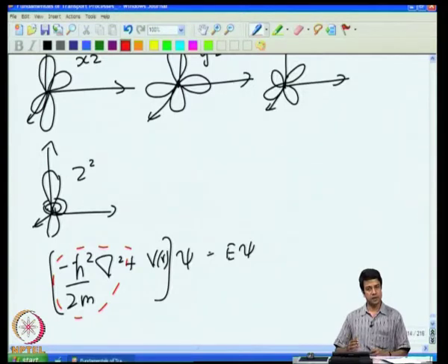For the unsteady heat conduction, you get spherical Bessel functions. In this particular case, for the steady diffusion equation, I get two sets of functions, one of which increases proportional to r to the power n, the other decreases proportional to 1 over r to the power n plus 1, called the increasing and the decreasing harmonics respectively.